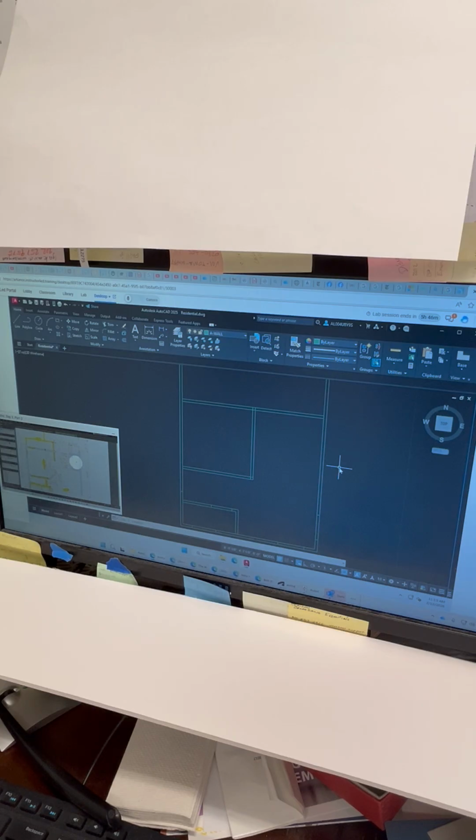All right, now this is a little tiny bit different than the other things that we've done. So basically what we're going to do is offset this inside line on the east wall, 2'1.5". And then we're going to offset this bottom line 4'2", okay? But here's the tricky part. This is going to the outside face. So what we're going to do is offset 3.5 inches up from there, okay?